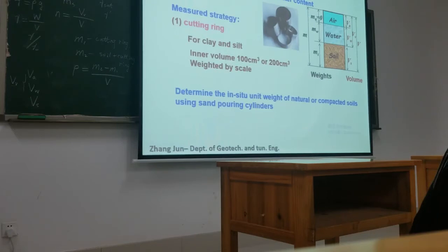the method is not convenient. So some methods, sand replacement method or water replacement method, are used for in situ unit weight of natural or compacted soil.